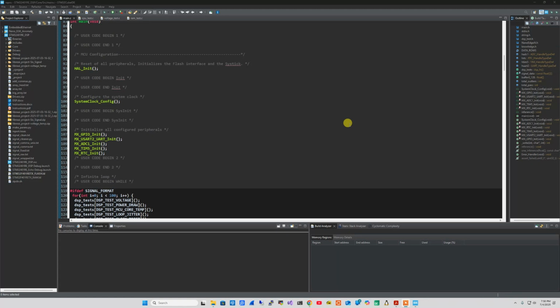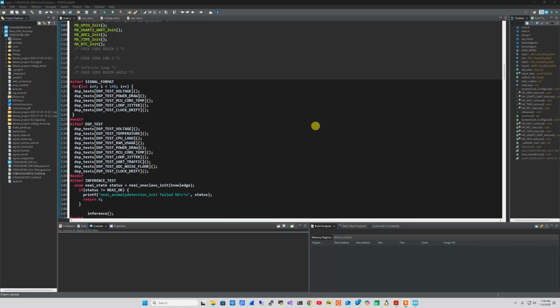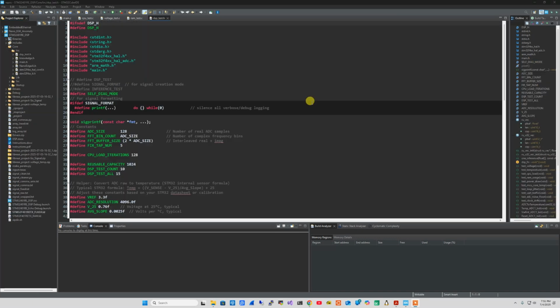I have another video that people like to watch where I get a Keras model onto a microcontroller, but that's very resource heavy. I had to use an H7 board for that to work. And this is the way to go moving forward for microcontrollers, I believe. So right now, rather than having runtime control of these modes I'm speaking of, I'm using conditional compilation. It's just more stable, so you can compile it and run with these different flags. And I'll show you where those flags are.